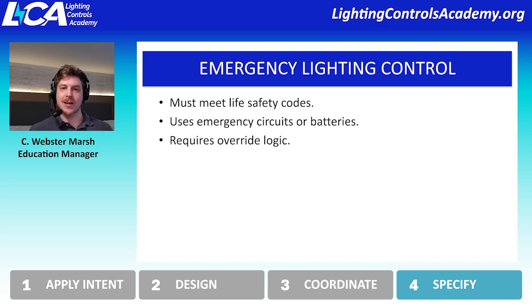It used to be full output. It is no longer just full output. We can have certain intensity values now, but what you need to do is make sure that your lighting is going to its emergency state under emergency conditions, either with a loss of power sensing circuit or with a fire alarm activation in some cases.